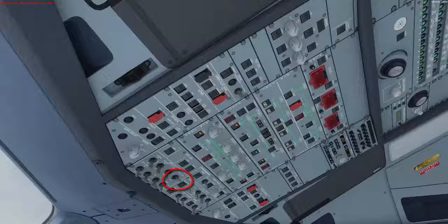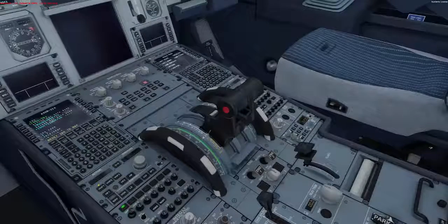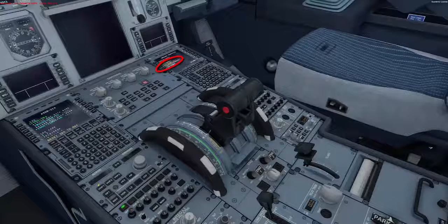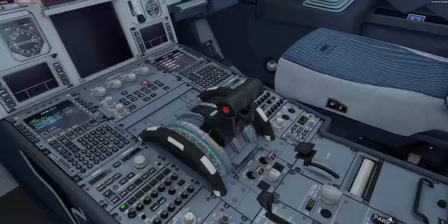And now we'll drop down to the right hand side CDU and attach our ground services. So press the ground services button and you can see they're all there. This was set up because we set the system to cold and dark, and that's the default setting for cold and dark. At this point I load the configuration for fuel and passengers.